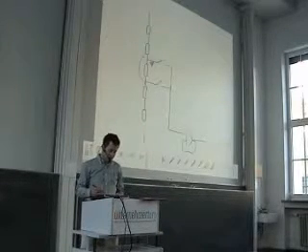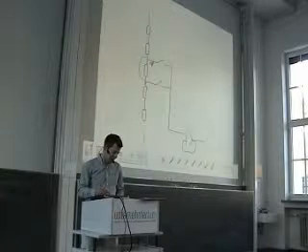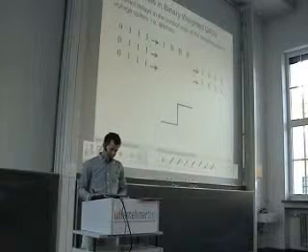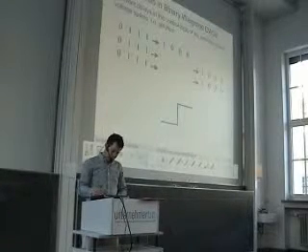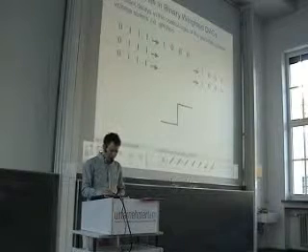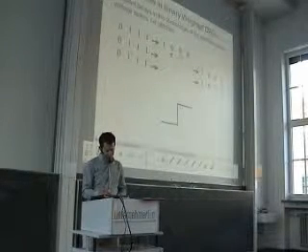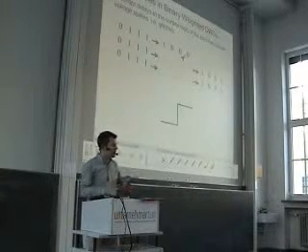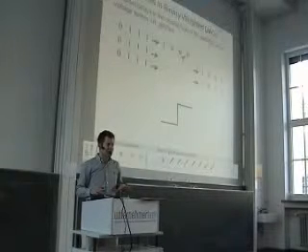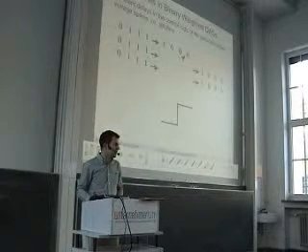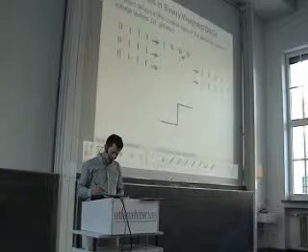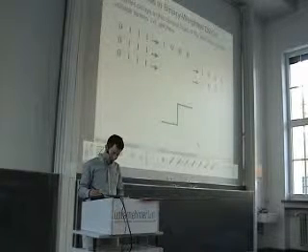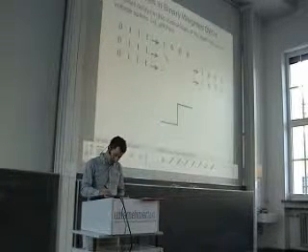There is another effect that can happen, especially in binary weighted DACs, which is a dynamic one. Look, if we switch again from 0111 to 1000, let's assume that the control signals of the switches do not all have the same delay. So what could happen is that the control signal for the MSB is pretty fast. So we get the switches first.